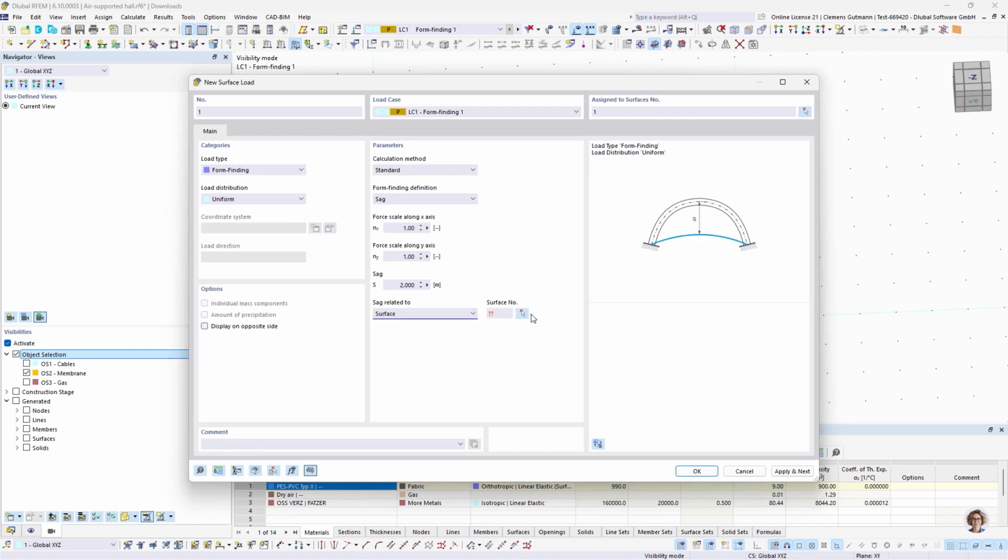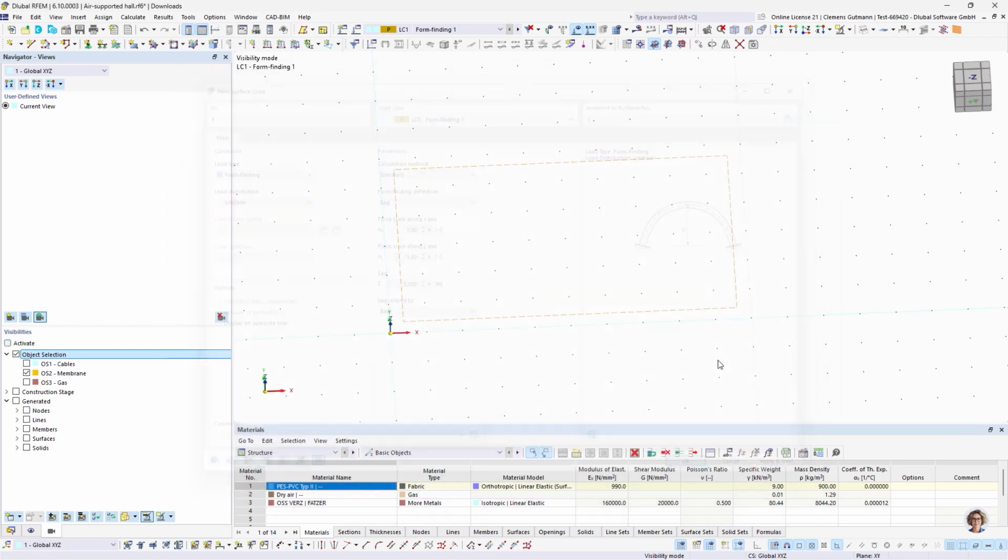So this is maybe for air cushions where you have several layers of foil and you want to use another foil surface as a reference to create a certain distance between 2 foil surfaces. I'm using the base option today as this is fine for me, and then I hit apply.